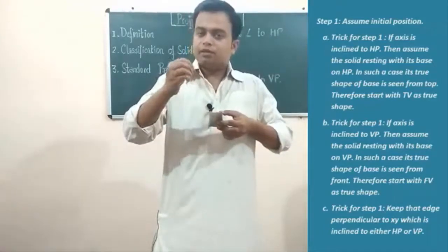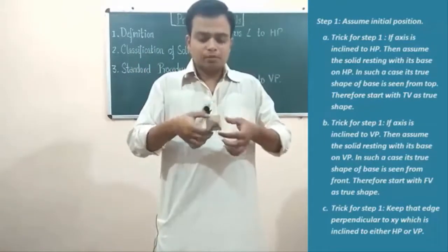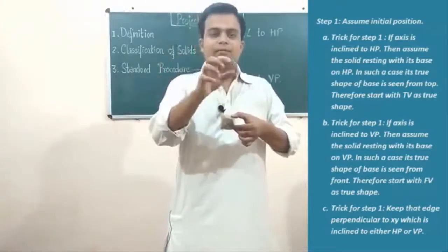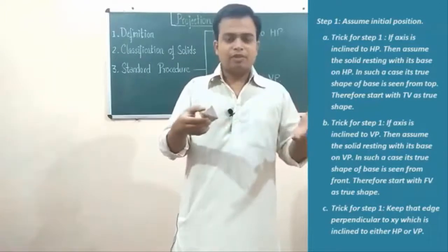And then again, you need to ask the same question to yourself. From where can you see the true shape of this base? Okay, the true shape of the base can be seen from the front. Therefore, you have to begin by making the front view first. So always remember this logic. This is going to be very beneficial for you.